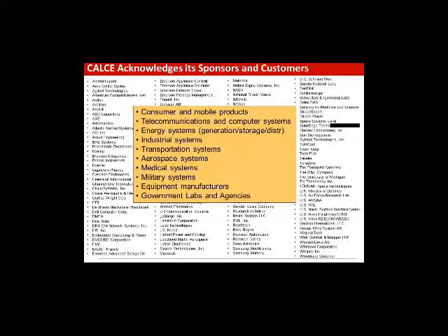But a couple of items besides visual are material characterization, which I dwelled on a little bit, because anything, be it the outside lid finish, the lead material, or, if you're looking internally, the die attach material, are specific materials, and making a judgment on whether it's supposed to be the authentic one or not can help us.